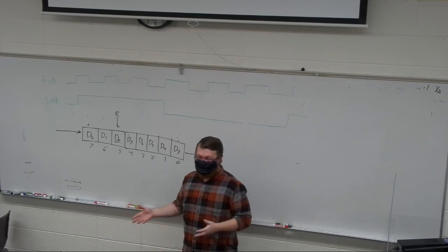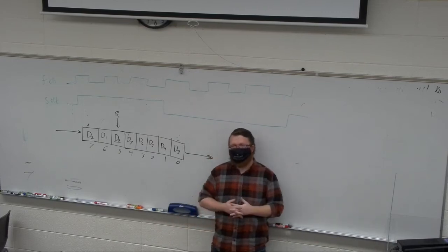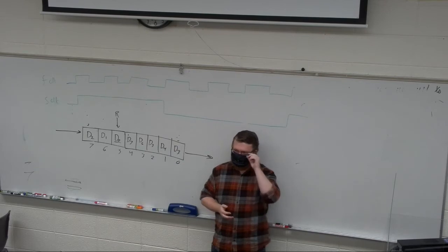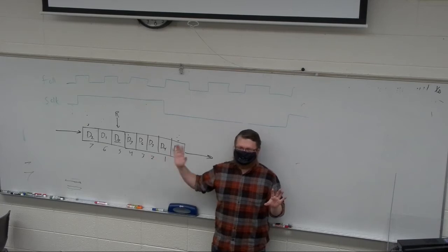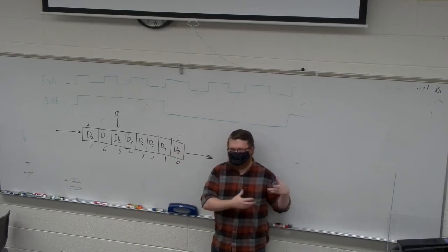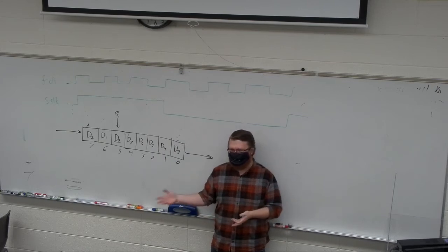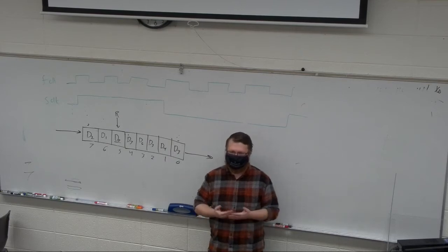Now, I have had to write my own asynchronous FIFOs. Unfortunately, this has happened because at one point I was using Lattice, which is a type of FPGA as opposed to Xilinx or Altera. Lattice is another kind, and they specialize in low power stuff. I can't use an Altera, for example, or Xilinx IP core on a Lattice FPGA. So I have to use Lattice's. Unfortunately, we weren't paying for their advanced license. In their case, we didn't have access to the dual clock or asynchronous FIFO. So it is possible that you have to write your own.